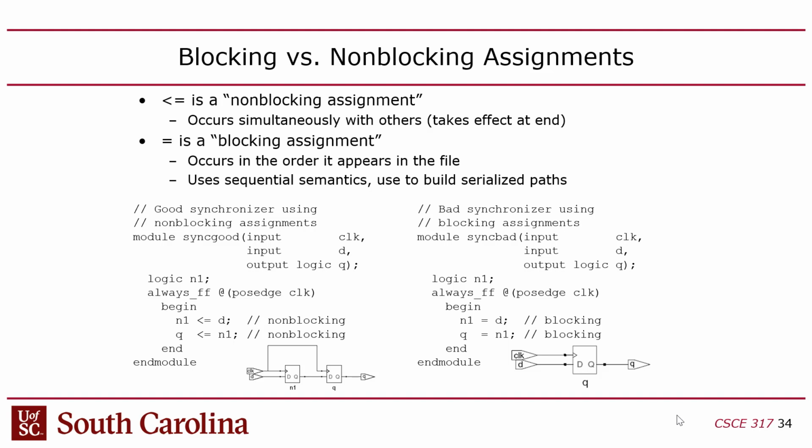Over here, if I use just the equal sign, then what it's going to do is essentially take this value, N1, and substitute D into where I had N1 in the line below. So this is redundant, because this will just end up creating one flip-flop.